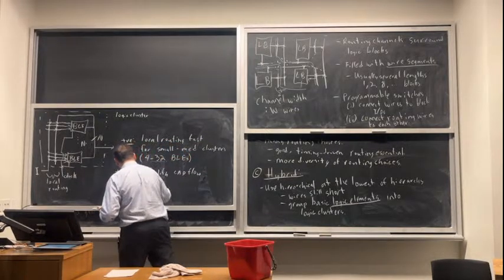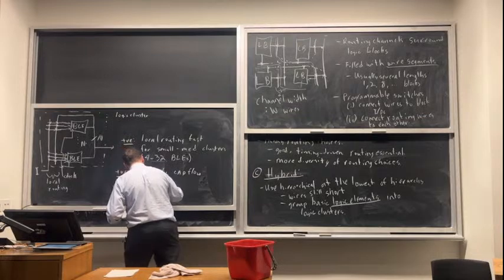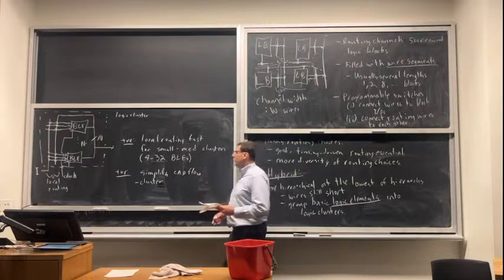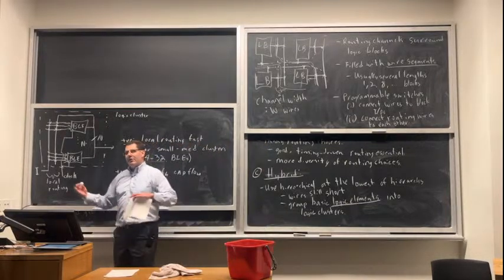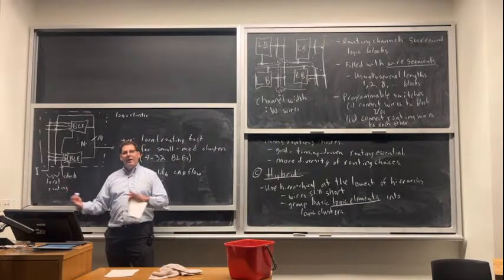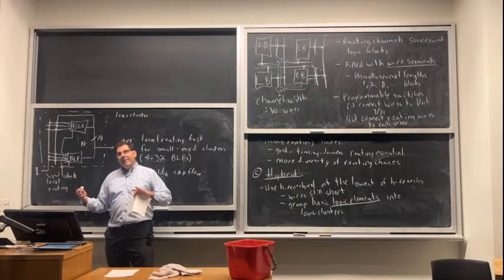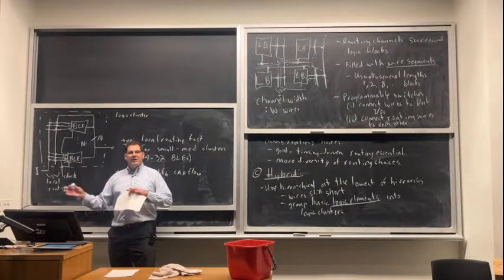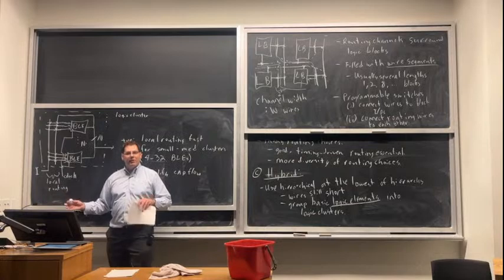Okay, so to simplify the CAD flow, basically you don't have to do this, but you can choose to do a clustering step, which is the same thing as partitioning. You're trying to cut up your circuit so that not many nets are cut but go between partitions.